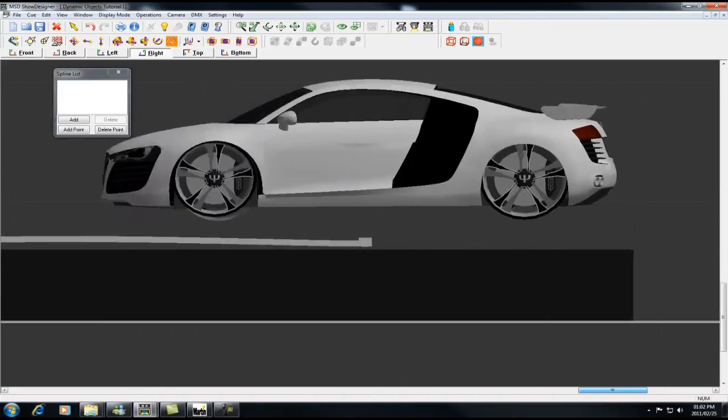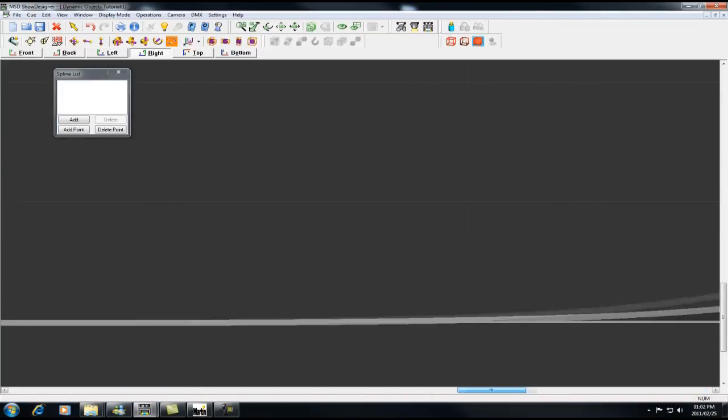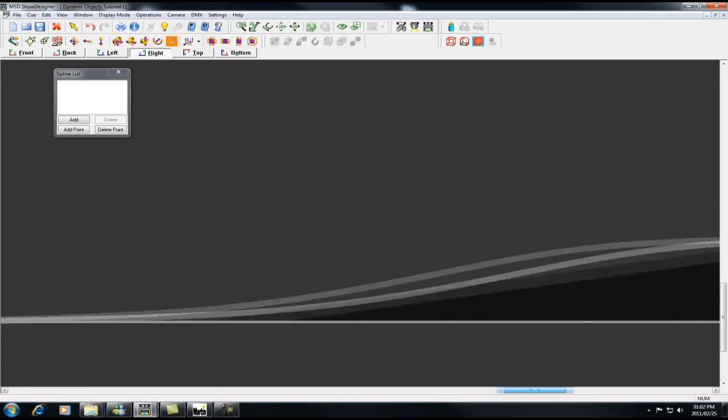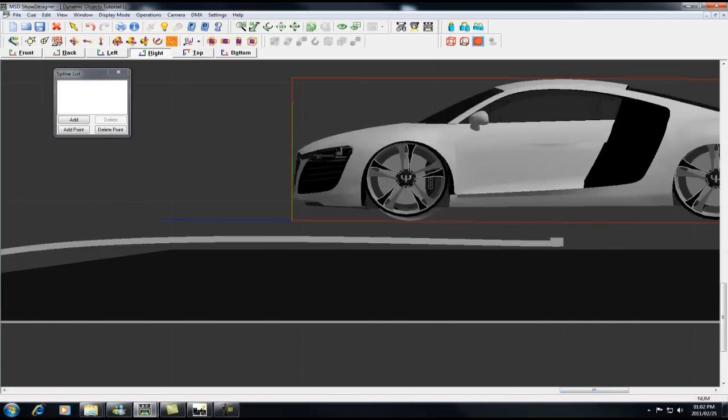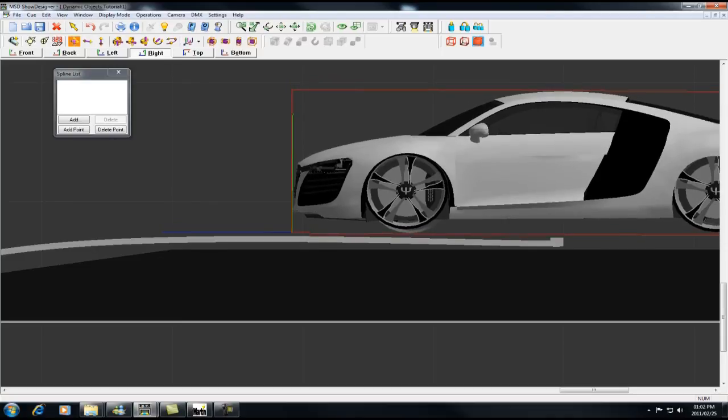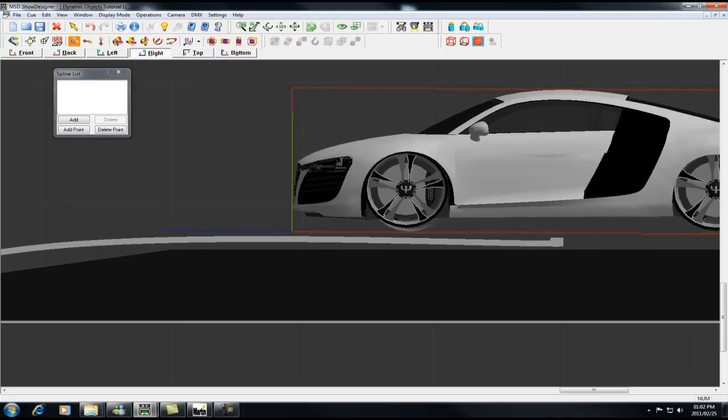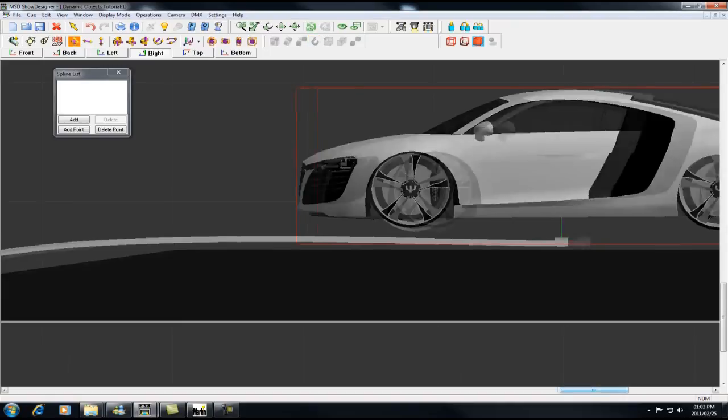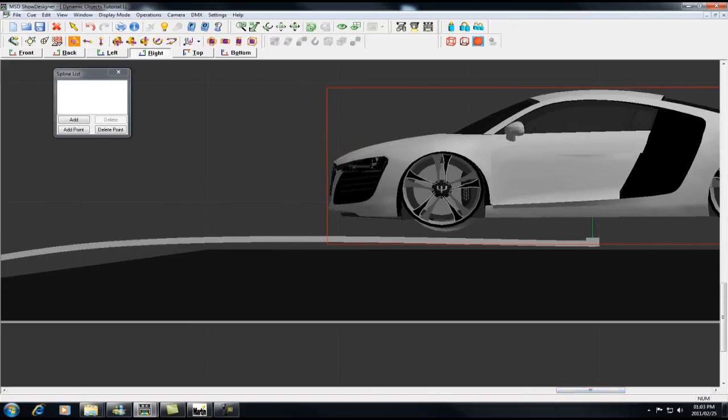What I've effectively done is that I have created a track for the car to run on. I then bring my car down a bit, and as before, connect the pick to the movable object. Select that, click on the pick, and attach it using this hook. Now that it's attached, the next thing to do is assign a motor to this dynamic object, just like I did with all the others. Go to DMX, Motor Map.